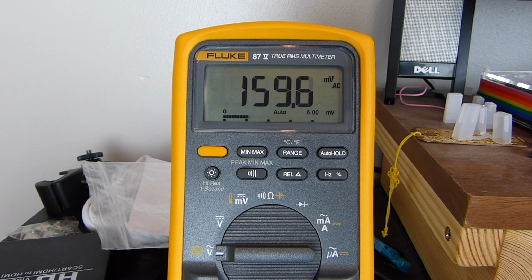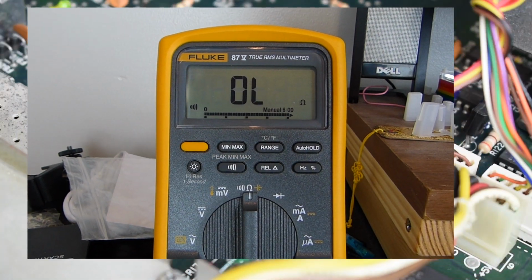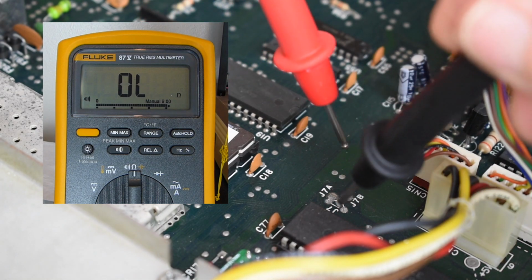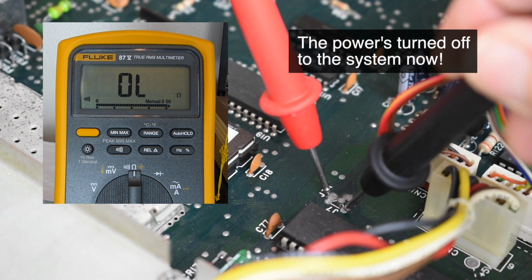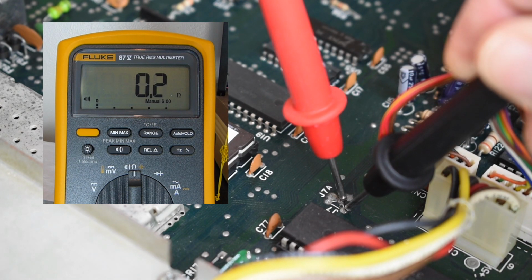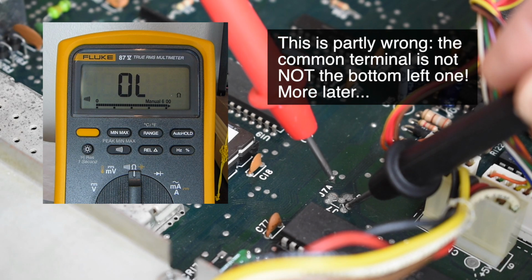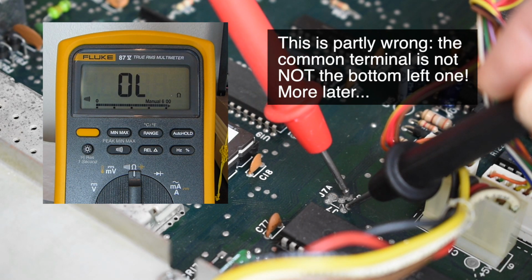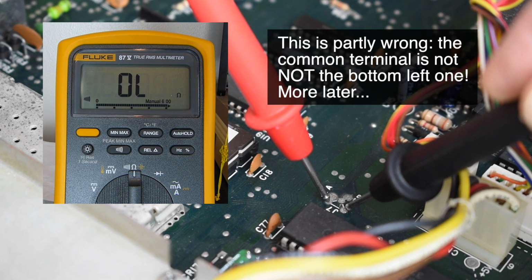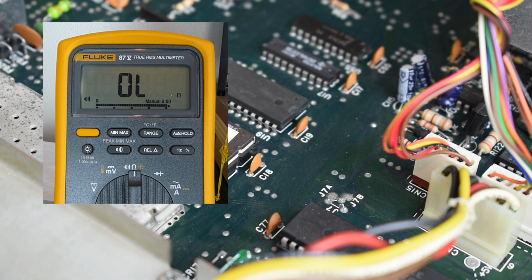Okay, so one last thing. If I change the multimeter over into continuity mode and take the two probes, we can see that the common terminal is not connected to the 7A jumper, but it is connected to the 7B jumper. The layout of this board is a bit confusing because the common part is actually connected to the right hand side of each of these jumpers, and it's the left hand side that's actually connected to the caps lock key and the 64 mode line. So anyway, we can confirm that the jumpers are connected to the caps lock key.